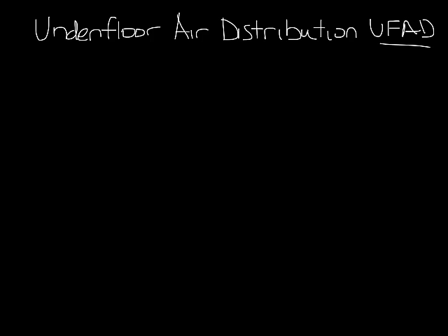So let's start with the basics. Underfloor air distribution systems use the underfloor area of a raised floor system as part of the HVAC system. Underfloor systems originated in Europe, but started gaining popularity in the U.S. about 15 to 20 years ago. Raised floor systems have been around a lot longer than that, but they were primarily used to run cable under computer room floors, and if you were supplying air, it was to cool the computers and equipment, not for personal comfort.